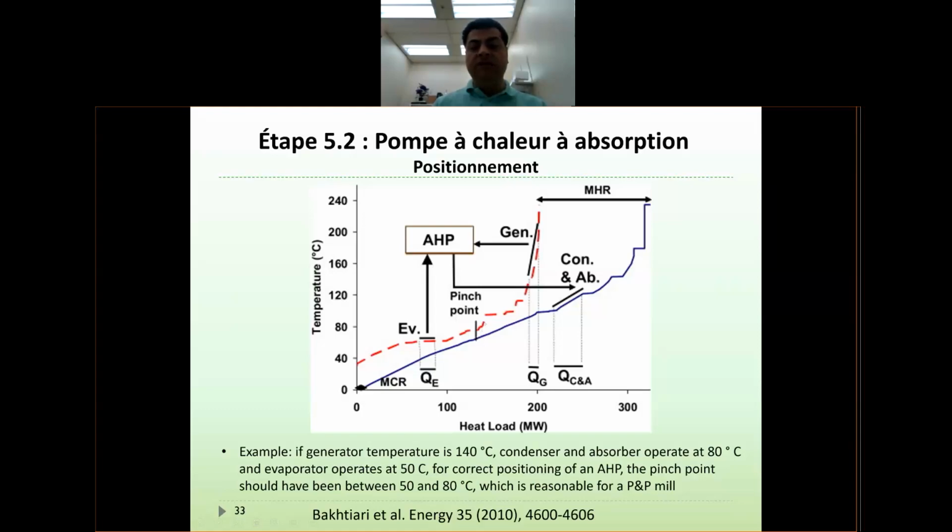You know what I mean? You can never consider a heat exchanger that crosses the pinch point, so that a hot stream above the pinch exchanges energy with cold streams below the pinch point. You can never do that.